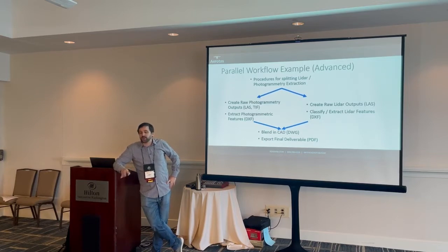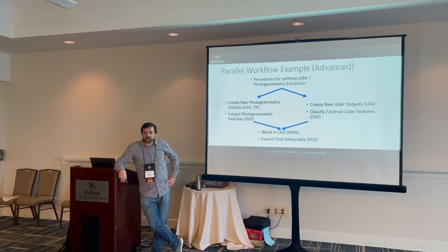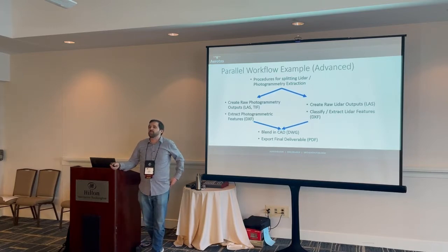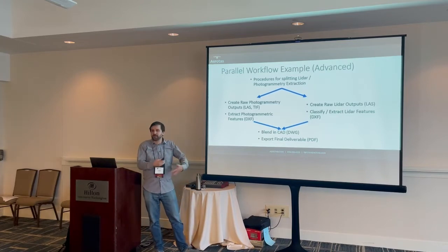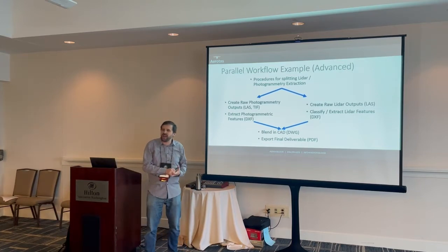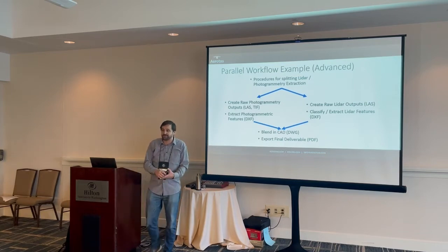We process our LiDAR data with LiDAR processing tools. I should point out, part of the reason we only do vegetated data with LiDAR is not just because photogrammetry is more accurate, but because LiDAR data is a pain in the butt to work with. It takes a lot of time. I argue it takes more time to process LiDAR data than it does for a comparable data set in photogrammetry. And maybe that's just because we've been doing photogrammetry so long that we've got that workflow rock solid. With LiDAR, we still have a little bit more room to improve our policies, our training, and all of that. But right now, working in the full resolution point cloud is a time-consuming method of extracting data.